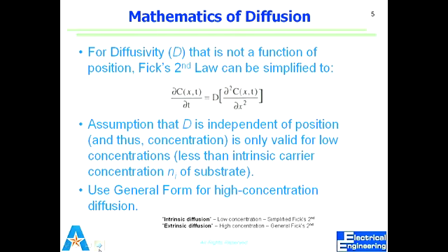Now, as a process engineer, what do I have to know for diffusion? I have this equipment where we do diffusion. What do I need to know? Temperature, time, and the concentration of dopant. Not just concentration, but also the crystal's lattice orientation, and fraction of dopant, right?